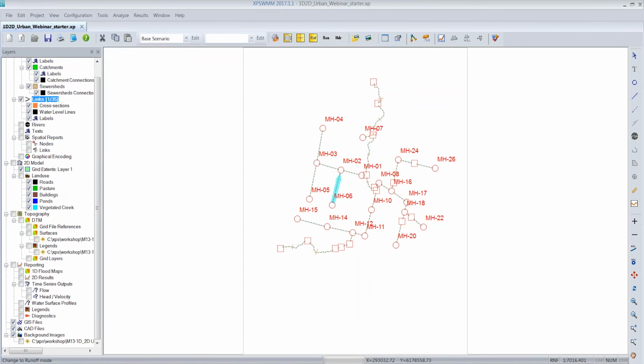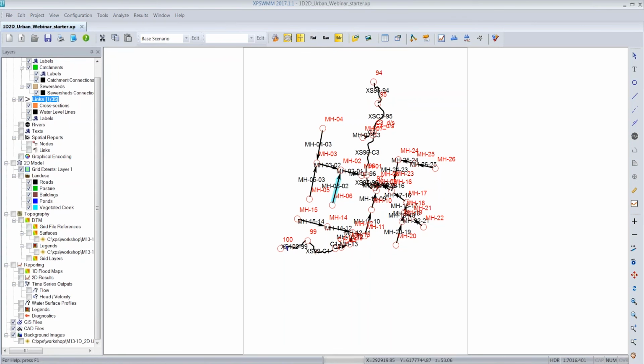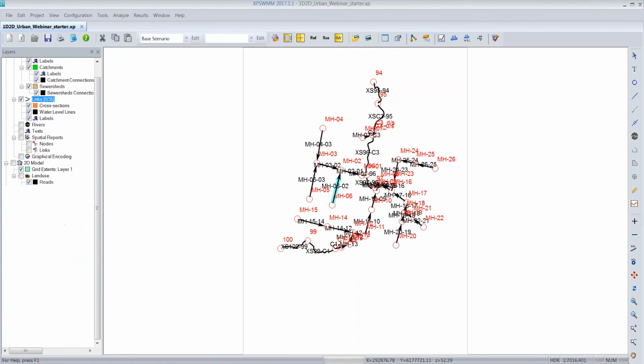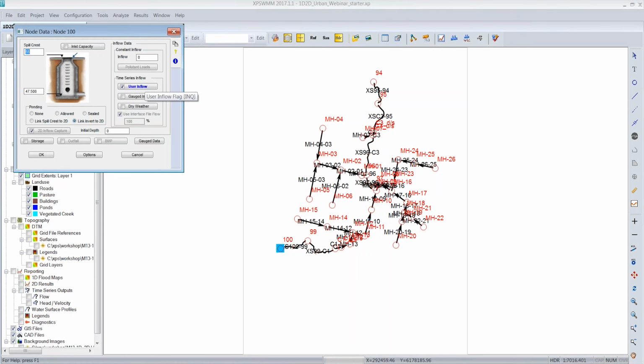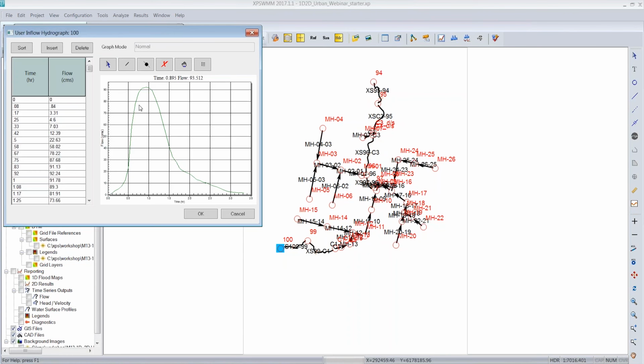So if I switch to the runoff mode, you'll see there's various nodes that are active, so they're going to be changing the rainfall to runoff. Also, at the most upstream part of the river, I am passing a hydrograph that represents perhaps an off-site flow that travels through the system, and I'm kind of measuring the impacts of the development in this area.